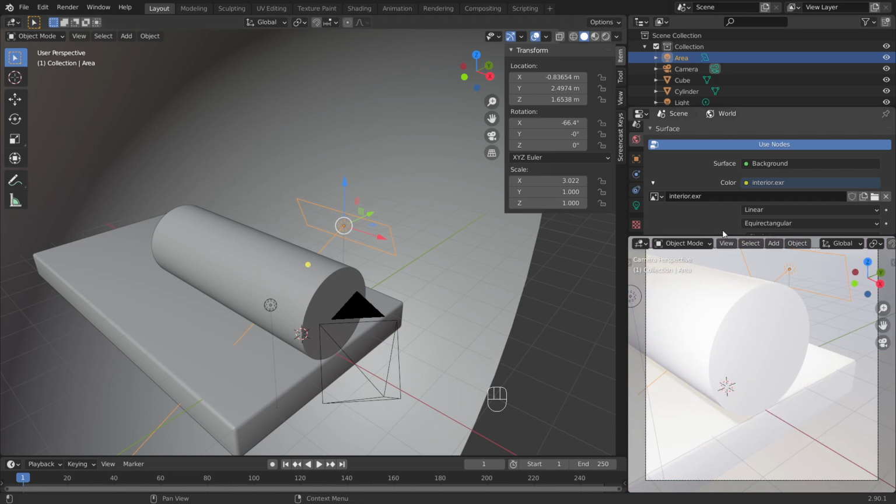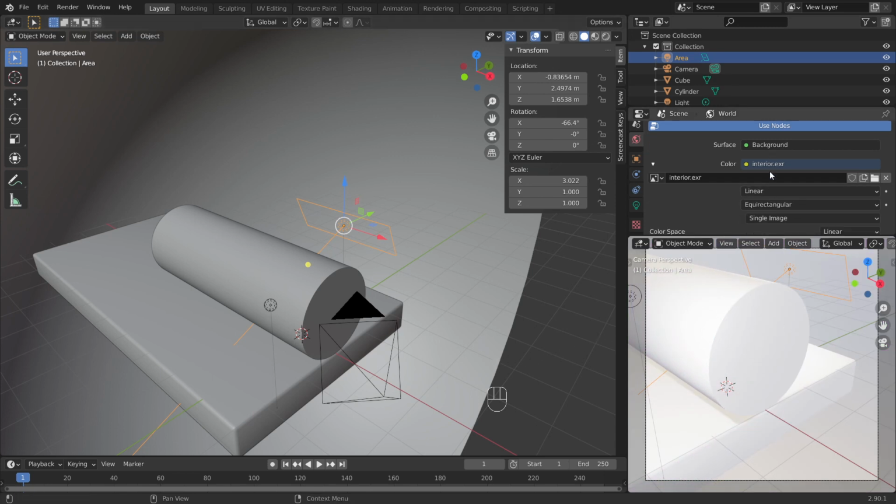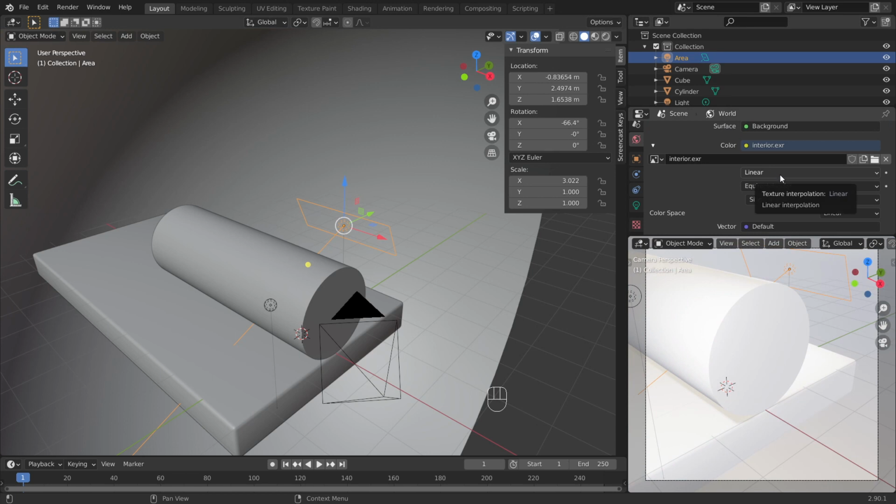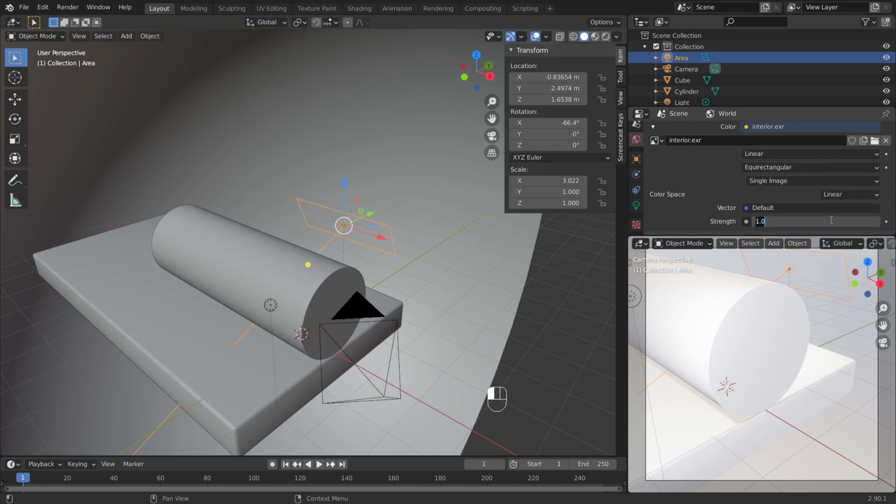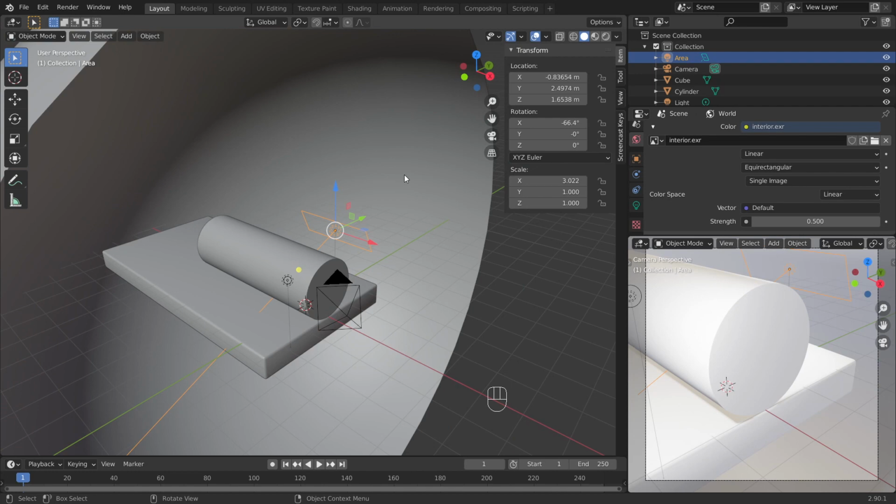And here's my ambient lighting. The last thing I'm going to do is to decrease the intensity to 0.5. And my lighting is pretty much done. And of course I can always come back and make adjustments later. With our modeling and lighting out of the way, let's work on the materials. We'll start with the easy ones first.